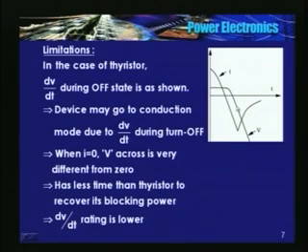When it is turning off, there is a high voltage appearing across the thyristor, the entire combination and across the triac. So there is another thyristor connected in anti-parallel. Now if this dV by dt is high, it may trigger the other thyristor when this current has become 0.